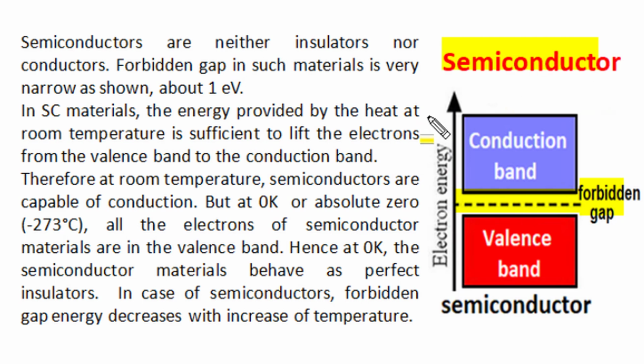But if we consider the same semiconductor at absolute zero temperature or 0 Kelvin or minus 273 degrees Celsius, then the highest energy possessed by electron is just midway of this forbidden gap, called Fermi energy level, and all electrons having energy less than this level are positioned only in valence band and no electron is in conduction band.